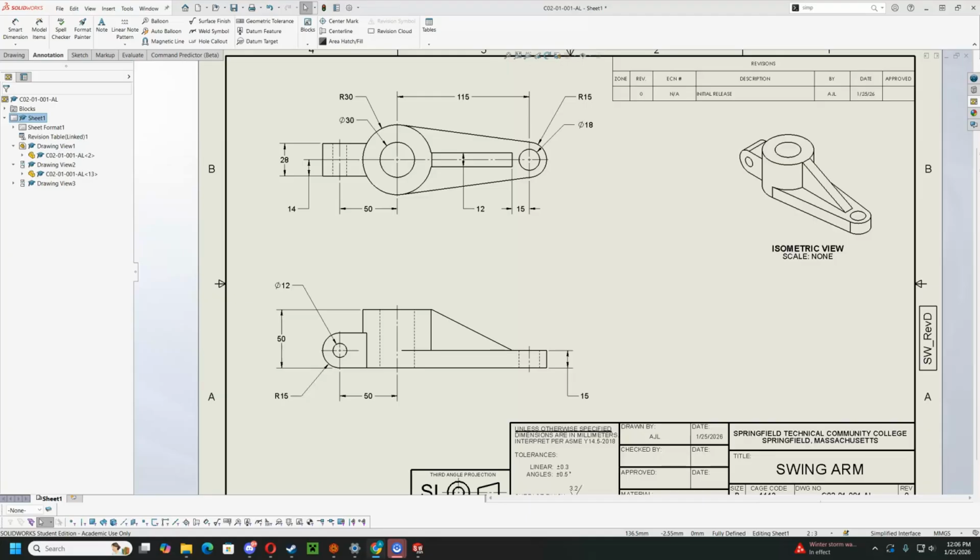All dimensions are listed. Can you model it? Well, we literally copied the dimensions from the print we used to model it, so I'm going to call that a good. If you're making your own drawing, it might not be a bad idea to take those dimensions and try to recreate it real quick. You'll find out very quickly if you miss something. No dimensions inside the part. All dimension text is clear and legible. Everything is nice and clear. There's no overlaps or anything preventing me from reading the dimensions.